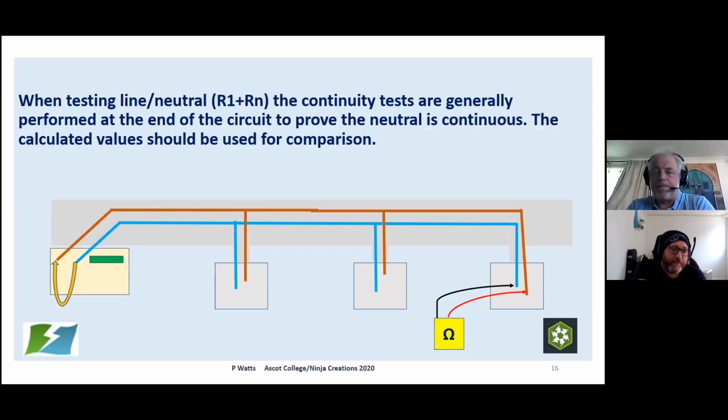From a design perspective, it's assumptions, because you're assuming you've got X trunking, then I don't know, 10, 20 other additional protective conductors, all probably connected at different positions within the trunking, making the trunking's resistance effective at different points. You're going down an avenue where your design goes in a completely different direction there.